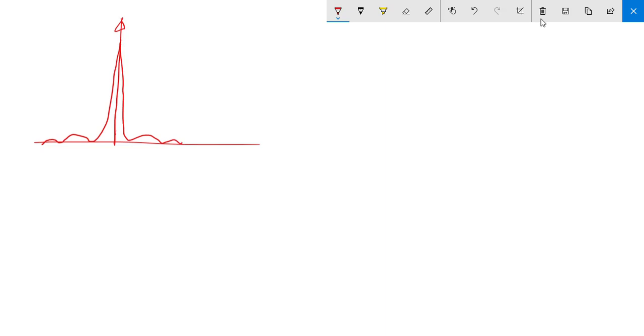So this is our original mass spectrum. Whatever random sequence you choose, the spectrum will be something like this. They will be different, but you will not actually experience the change with the naked eye. Basically, the change will not be drastic, because it's random and the frequency spectrum will always look something like this. The majority portion of the frequency spectrum will be concentrated at this low frequency region.